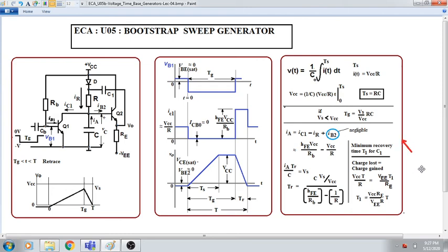And here in this particular case, this portion is blank because we cut it and used it at the beginning. Do you remember what we put here? Whenever this sweep does not reach VCC, the value here will be VCC by RC multiplied by TG. So that is what we have put there. If you want, you can remember that.